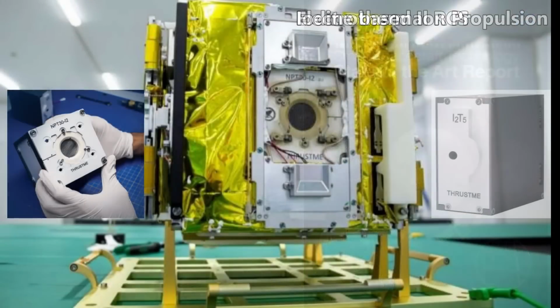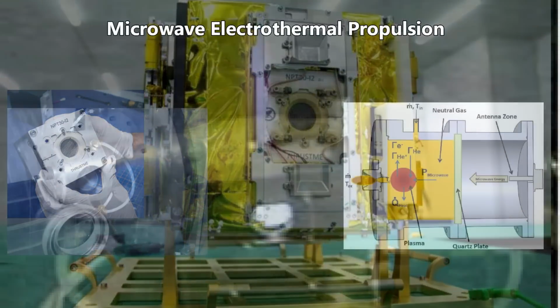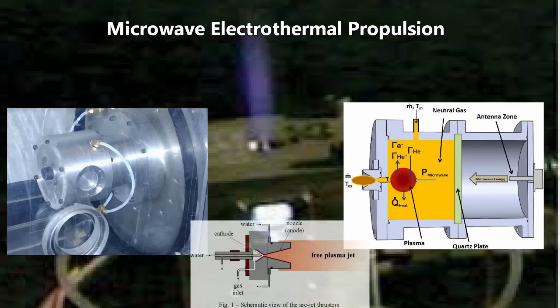They also have iodine-based ion and Hall thrusters for better performance, but these usually don't have the thrust necessary for RCS. And here we see a microwave electrothermal rocket engine called an MET. METs turn electricity into microwave frequency photons and use those microwaves to heat the water to a much higher temperature. This is a lot like an arc jet, but it does not need an electrode, improving endurance and reliability.